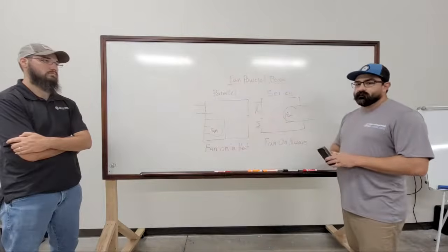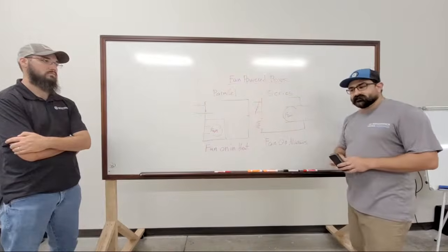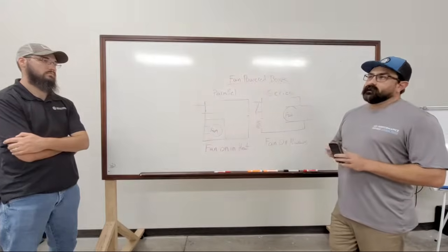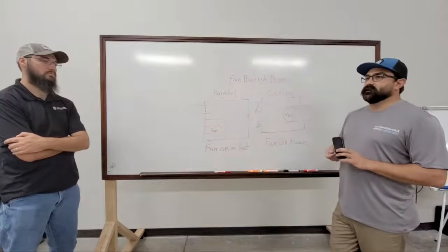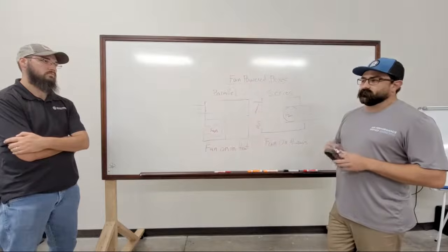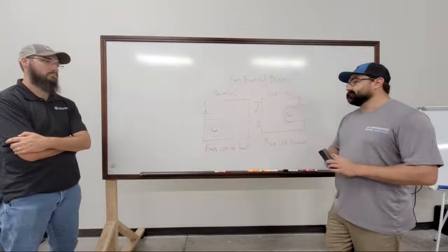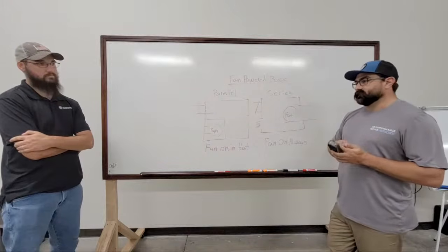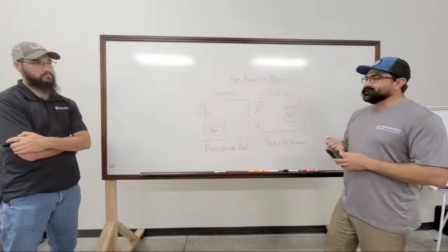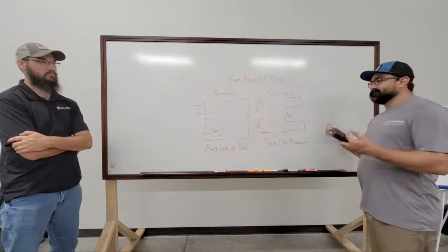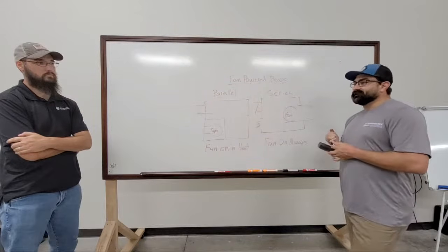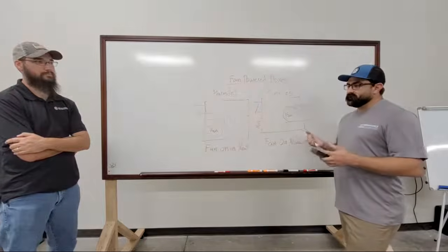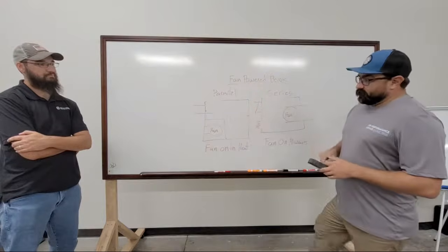We get a lot of complaints when customers change systems from a drop ceiling to an open concept with noise, with boxes cycling on and off. We've got a project right now that we're having some issues with noise because the tenant decided to move in and knock all the ceilings out, and sure enough, oh, we keep hearing these fans click on and off all day. Well, they're doing their job, keeping the space temperature, but you hear the fan come on.